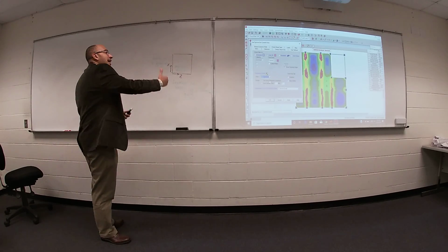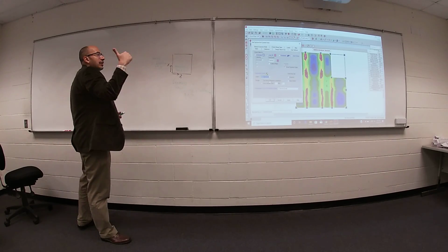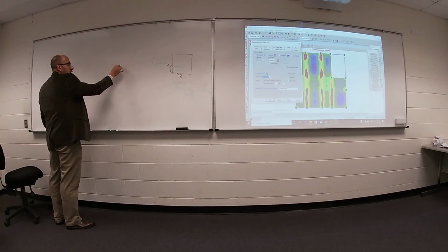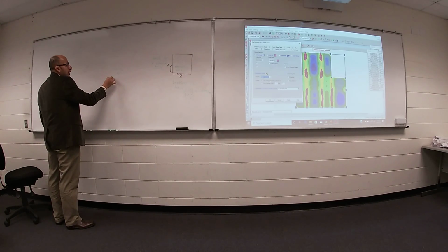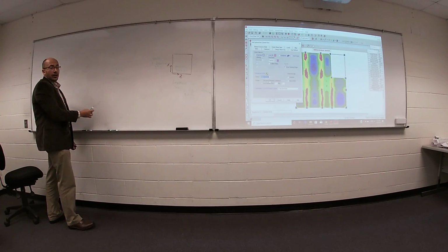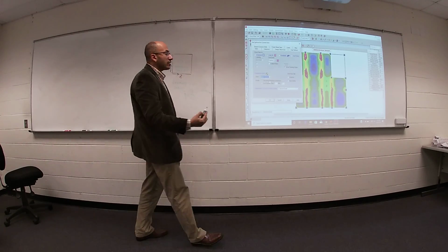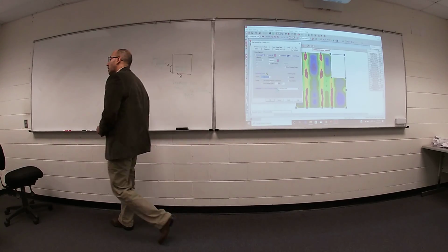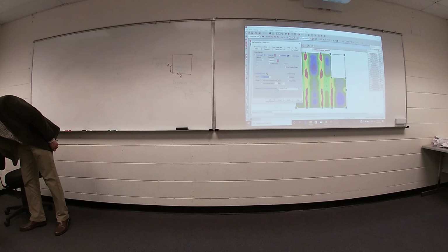So MZ. You would like to design how much steel reinforcement. Do you remember to design? We need 1.4 dead load or 1.2 dead load plus 1.6 live load. That's right? So which results you are going to use? Are you looking for results for serviceability combination or for strength combination?